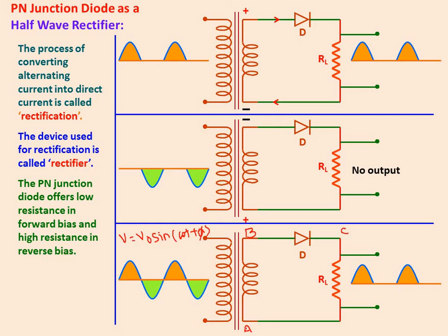And while through the resistor A is at low potential, what kind of connection is this? Forward bias. So now the diode is in forward bias condition and current passes through the load resistance in the direction C to A like this. It conducts in the forward bias condition. Okay, right. Now the negative half cycle.